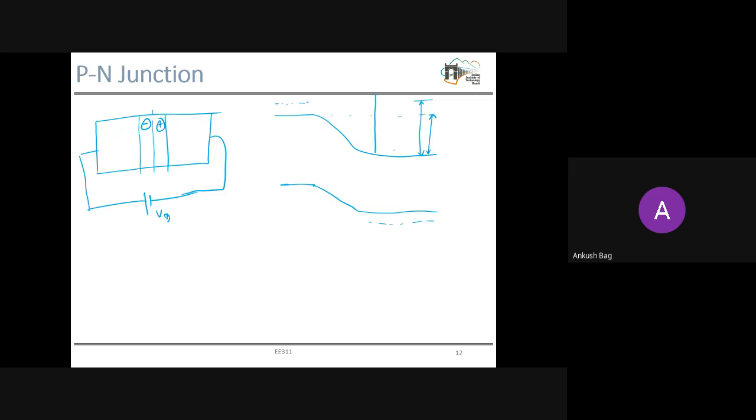Once again our electron carrier concentration will be something like this. See, these many carriers earlier were hot enough to cross this junction, and those were eventually balanced out by the drift of thermally generated carriers, that is, thermal generation within the depletion region.